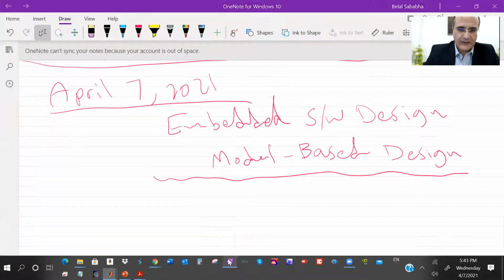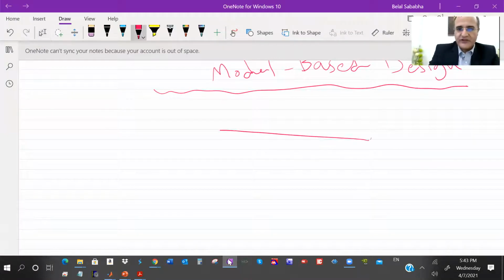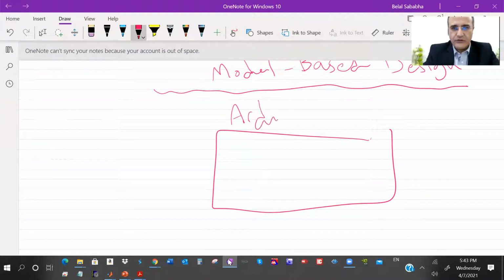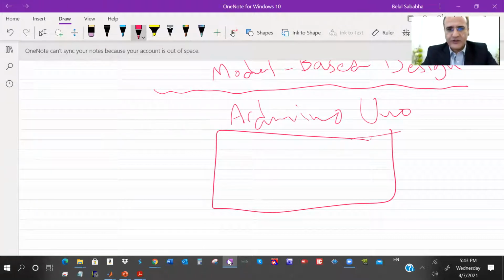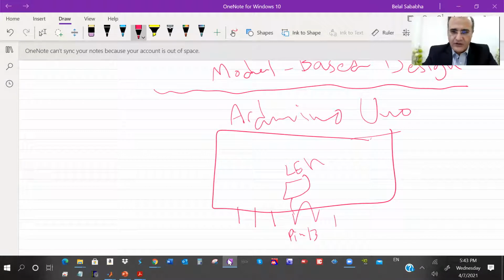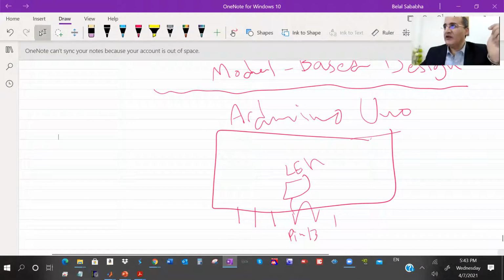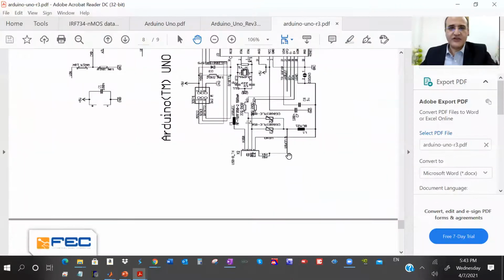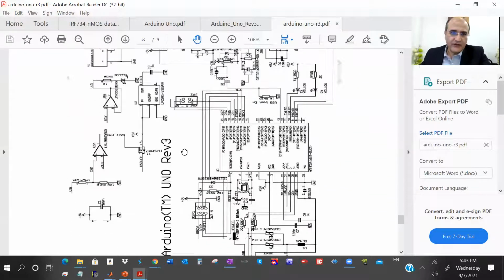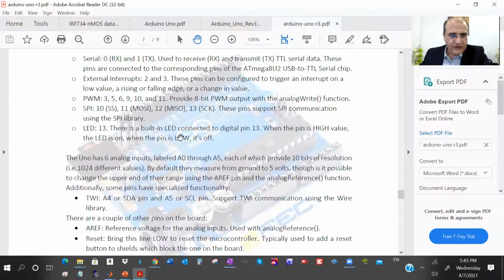First, the Arduino board. This is the Arduino Uno. There's an Arduino Mega, you know. The Uno is the smallest, cheapest, simplest. It has a lot of pins. Okay, one of the pins is already connected to an LED, which is pin 13. If you don't know, you can go back to the sheet of resources I just shared with you, to see where an LED is connected to what pin, and you can check the schematic, but it's even easier here.